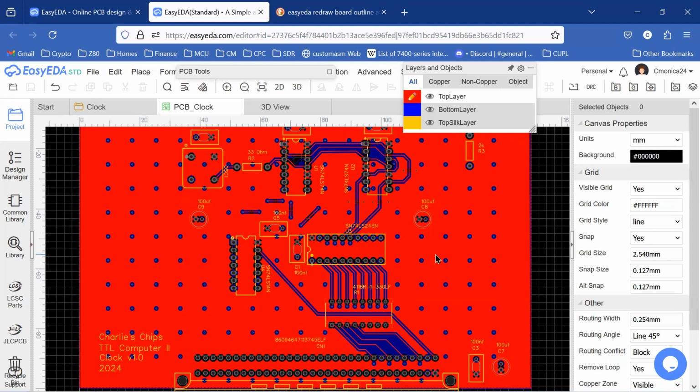For something like the back plane, the motherboard, I'll probably do manual routing for the whole thing. But I don't know. I'll try and see if this combination of auto routing and then going back a second pass and doing manual routing works when we get to my next board.